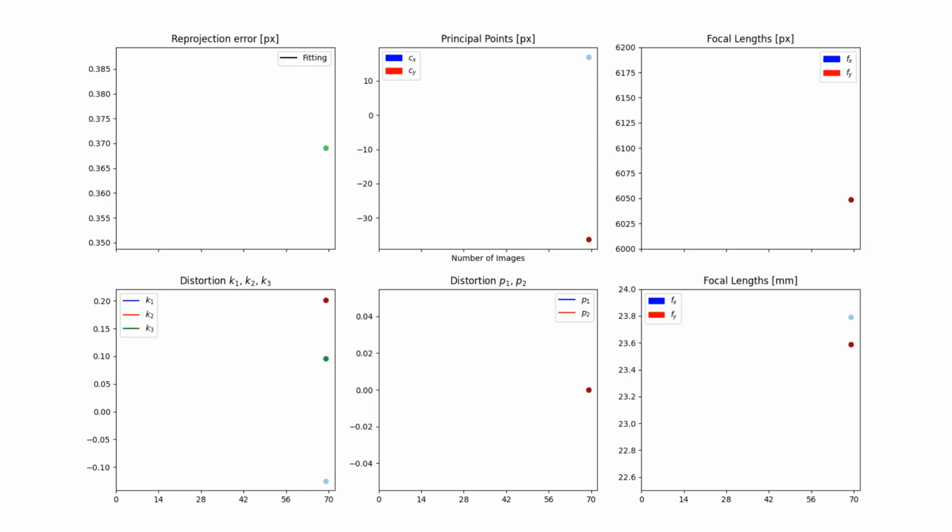Okay, so we've got these estimates and they seem reasonable. But how can we tell if they are accurate and reliable? The first thing to consider is that this reprojection error is calculated on the same images as were used for the calibration. A low value here doesn't guarantee that this output will also give a good result for other images. It doesn't tell us how well those results will generalize.